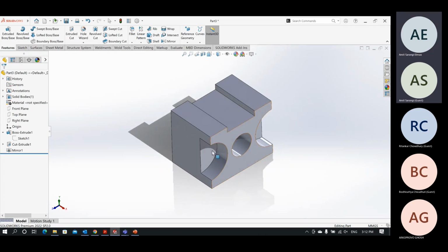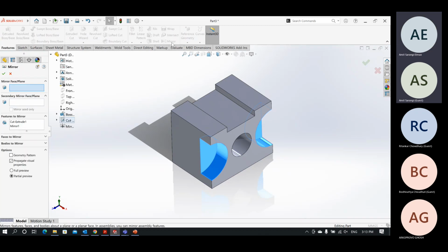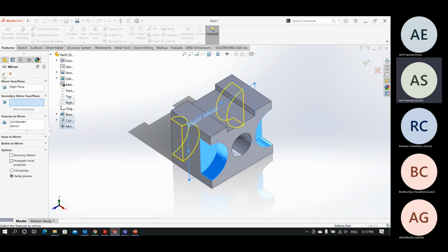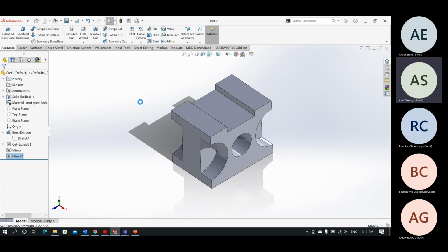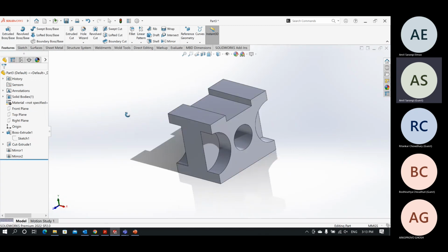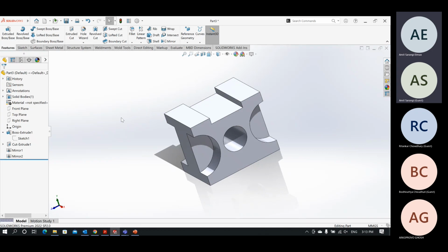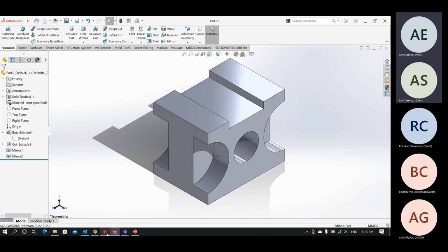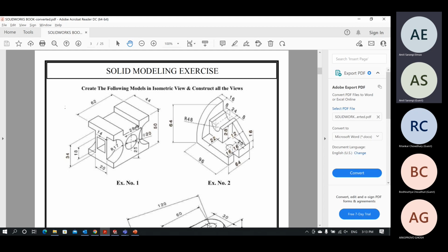Once both the mirrors are done, you can mirror it to the opposite side. How? Click on this, control, click on mirror, again click on mirror from the option. Now in this case, our mirror plane is our right plane. Click on OK. Done. Control 7 isometric view. See, I think it is correct. Our orientation is also perfectly fine.